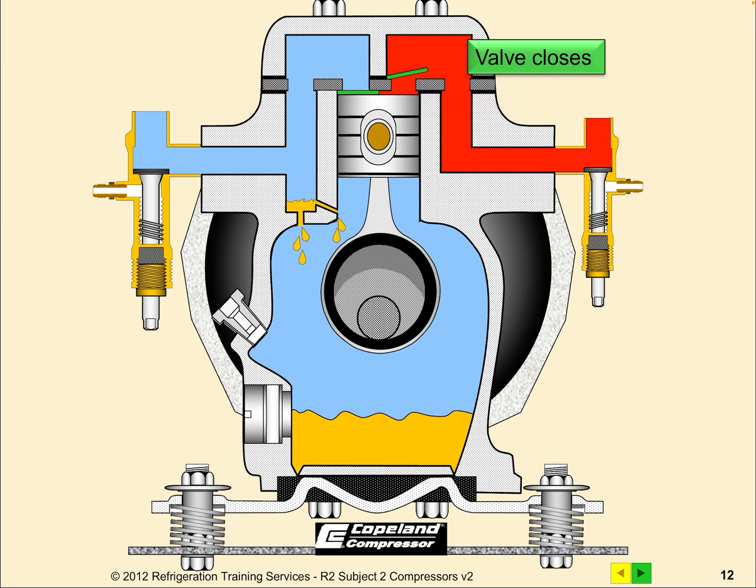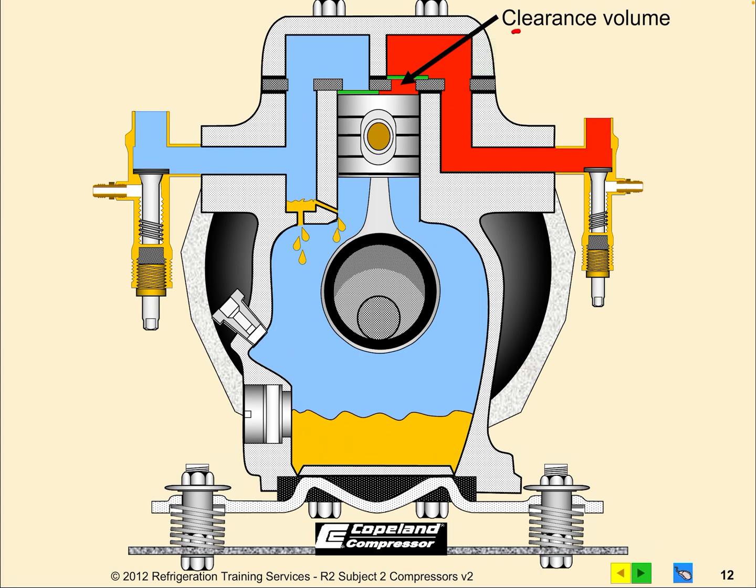So again, we'll go back to that compressor now, and here we're looking at the piston at top dead center. Now I can't make the space smaller, and here we're identifying the clearance volume, and that's the inefficiency. So we need a little bit of space there. Now that valve will close because there's no delta P anymore.